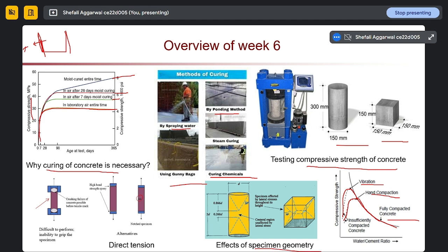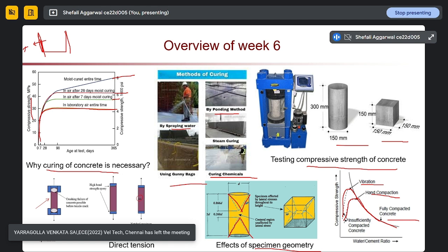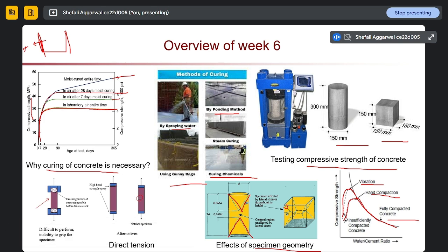With the same apparatus we have three types of plungers, which define the consistency, initial setting time and final setting time. So from the same apparatus we can calculate the normal consistency as well as the setting time of our cement material.